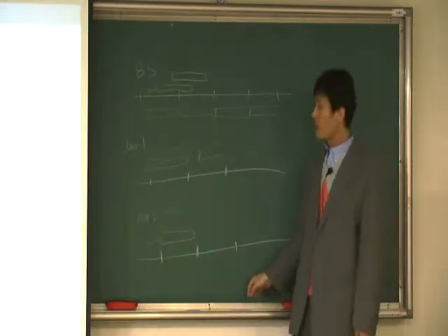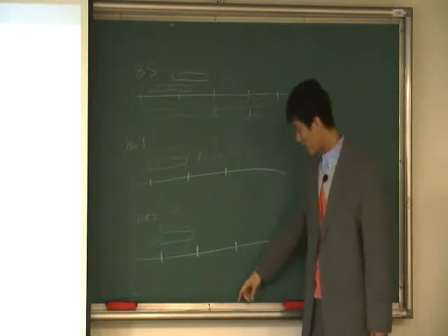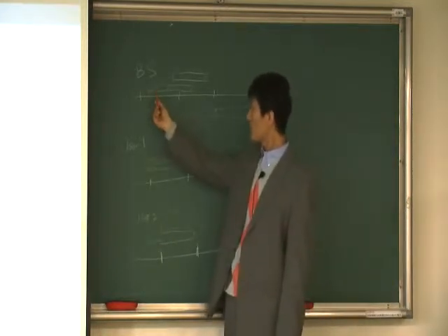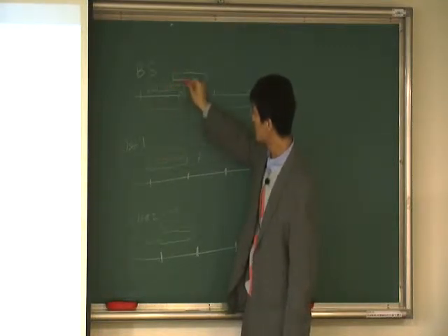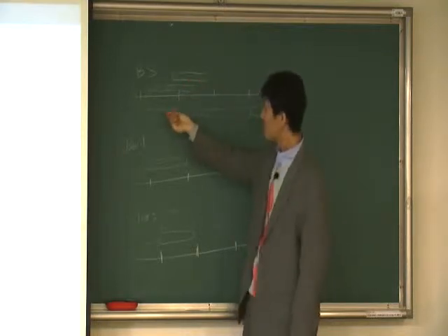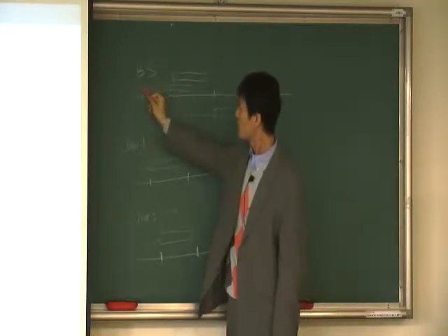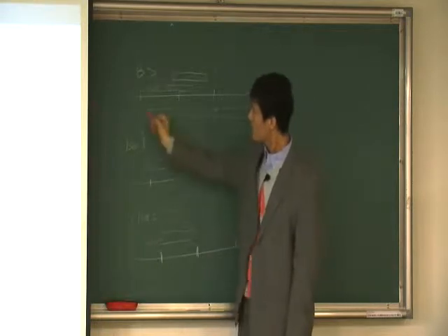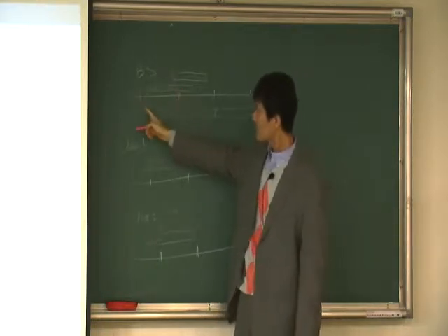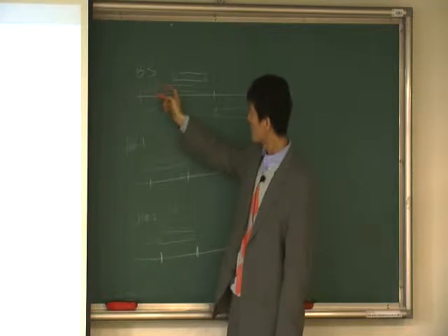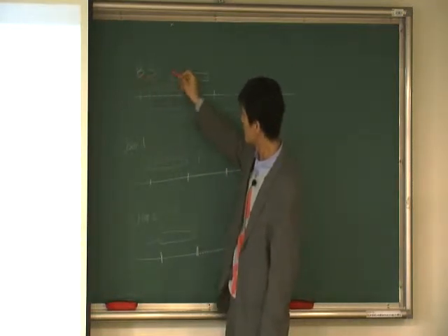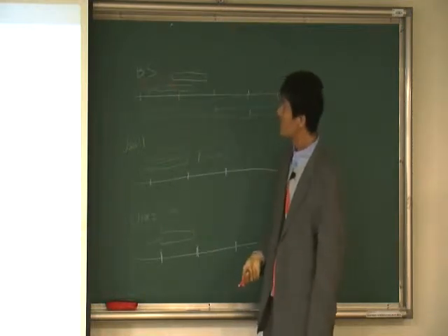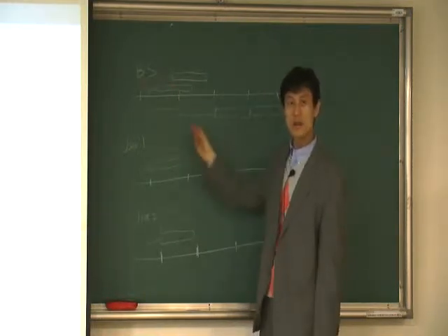Now the base station finds out, oh, looks like this is user 1. The packet has an ID. So this is user 1, this is user 2. Looks like user 1, you are this much far away from my time. This is the uplink time for the base station. User 2, looks like you have this much time offset. Now the base station knows it.